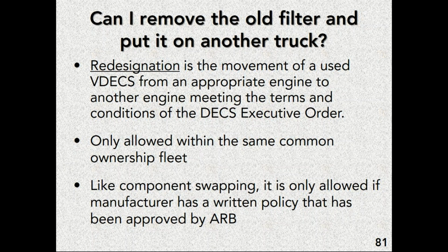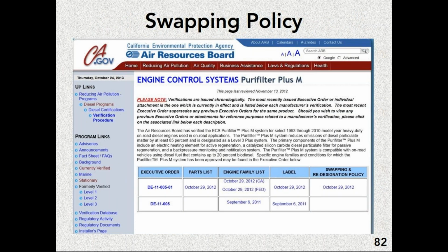You want to make sure that the manufacturer of the filter has a redesignation agreement on file with the Air Resources Board, and that you own both the truck that was wrecked and the new truck, because otherwise it's not allowed. You can see the swapping and redesignation agreements on this particular filter on the far right hand side. That's going to be a PDF that tells you what actually is allowed.